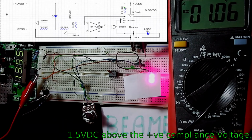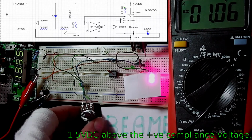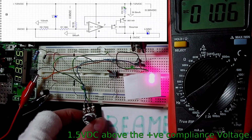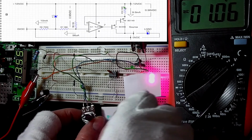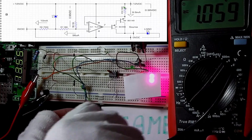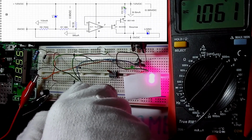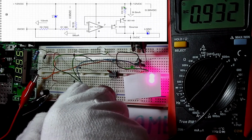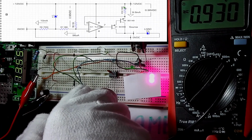Now I've got the meter set across R10 again, and I'll adjust the potentiometer. We're reading 1.06 volts, so let's drop down a range. There we are. Now again I'll do the linear drop with a rotational pot.